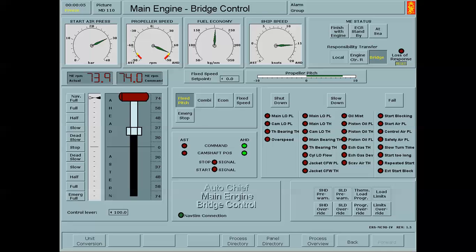The reason is that over time, with hull deformations and with fouling of the hull, the load would go up on that engine to maintain your service speed. So these ships typically are designed so that the engine is sufficiently oversized that once under these fouled conditions, the engine will be able to propel the ship at service speed.